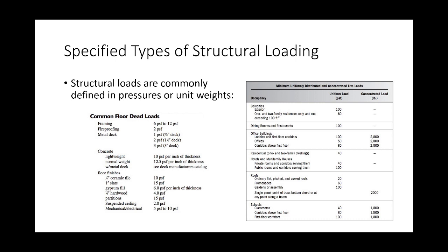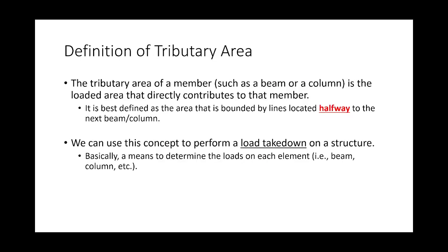Whatever the structure is being used for, that changes the type of load that we apply. But if you look, you can see that those loads are expressed in pounds per square foot. When have we ever dealt with that in here? Have we ever dealt with a load that was a PSF? No, we have a truss and it's got 12 kips on the joint. 12 kips on the joint is not this, right? Okay, so that's different. How do we handle that? Well, we handle that through the concept called tributary area.